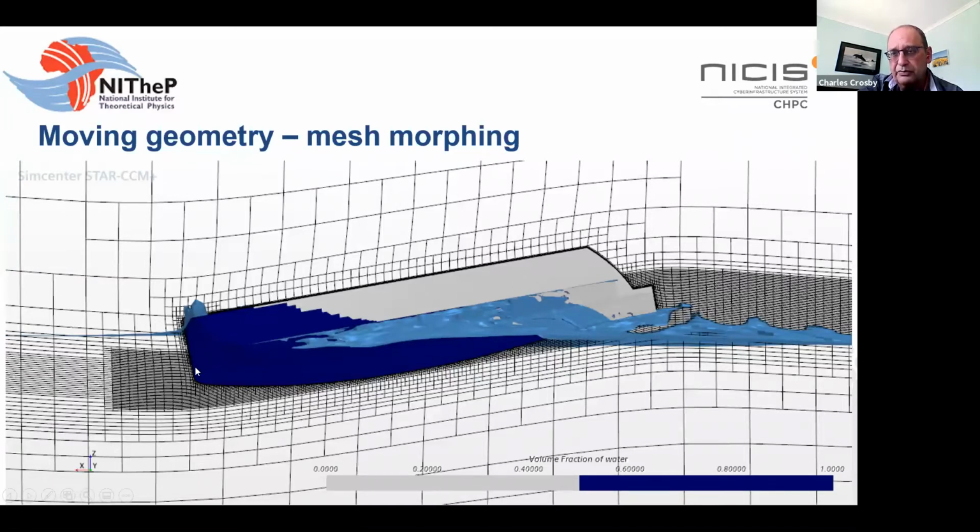That's a good way of preventing the grid cells from folding over each other. And then you have a smooth deflection back into the background mesh. So you allow it to move up to a certain distance away. And you may use a Laplace solver to get you a smooth distortion of the grid. And these methods have become surprisingly effective.